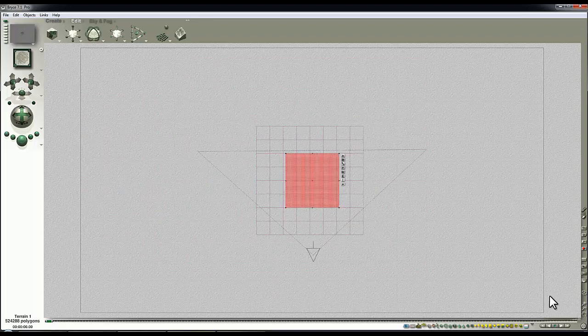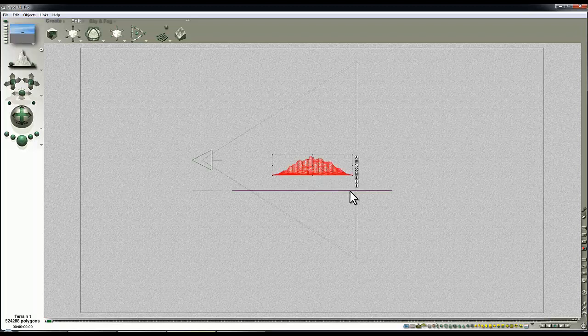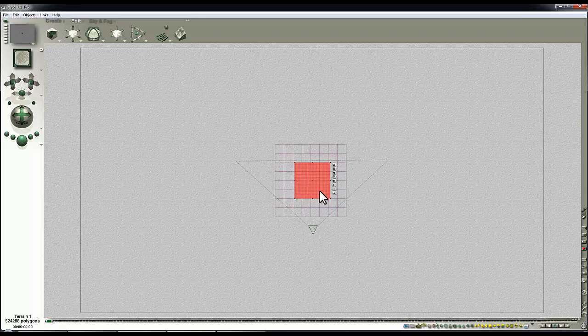So like if I press minus now, so if for example I'd lost track of our terrain in the overhead view and I couldn't work out how to get it back into view, you could switch to a side view 3. All the views are bound to either 1, 2, 3, 4 or 5, 6, that kind of thing. Then if you switch to one of the other views and you can select it like so, then when you switch back to the overhead view, minus or plus will re-center it in that view, which makes it a lot easier to find. So there's another reason not to use plus or minus, because it does tend to move things around in the perspective view, and then could result in odd perspectives because you'll have moved the vanishing points around.